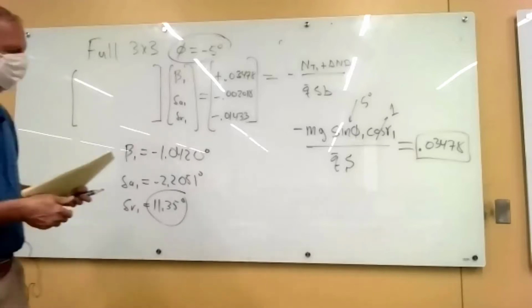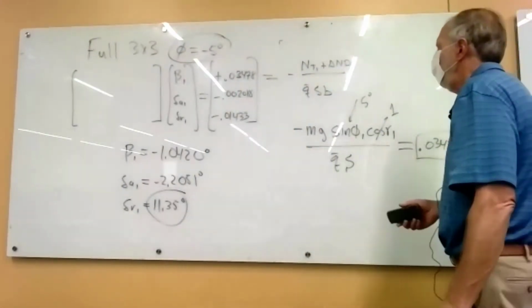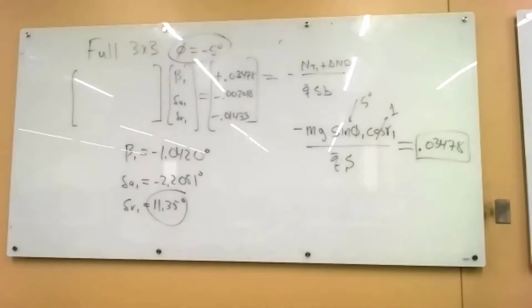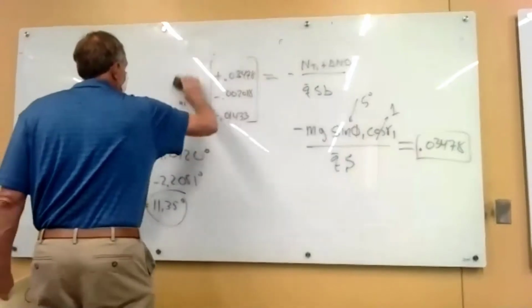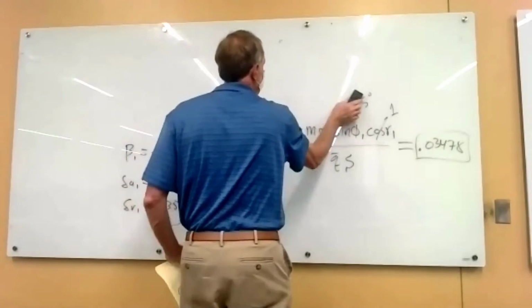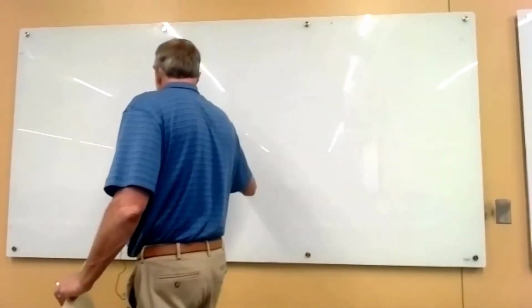So all this leads to calculating how slow can you go and still operate the airplane with an engine out. Remember we talked about if the velocity goes down, you get less rudder power, which means you need more and more rudder to keep from crashing. So what you want to calculate is something called the minimum controllable speed. And it comes from that same formula that we used to calculate the approximate rudder.